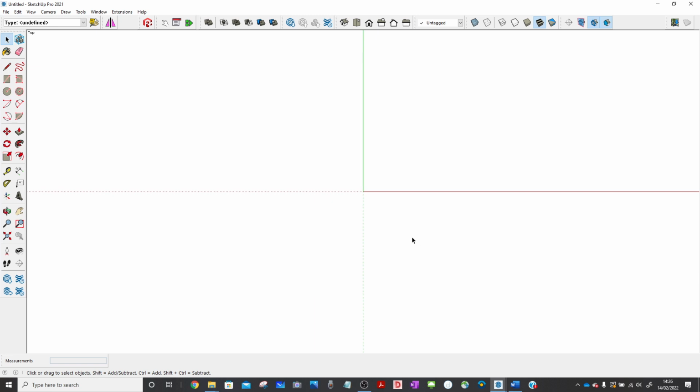Now, I'm going to create for you 3 simple mass elements, or just blocks, a cube if you will, of timber, concrete and steel. I'll put only one piece of data in there, and that will be the mean density. That's the exact same principle if you've worked out your global warming potential, which is CO2 equivalent, or your embodied energy, which is in kilojoules. You can put it straight into your model, or you can extract the volume, which I'm going to do today, and then start using Excel if you want.